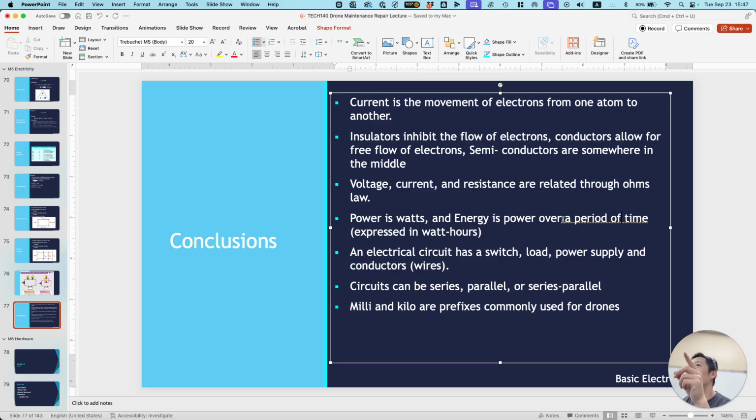So it's a bunch of 1.5 volt batteries. Is that in series or parallel for us to add up to 9 volts? Series. Okay. This thing is 4 cells that are wired in series. And that's what the S means. So the 4 tells you it's 4 cells. The S tells you it's wired in series.